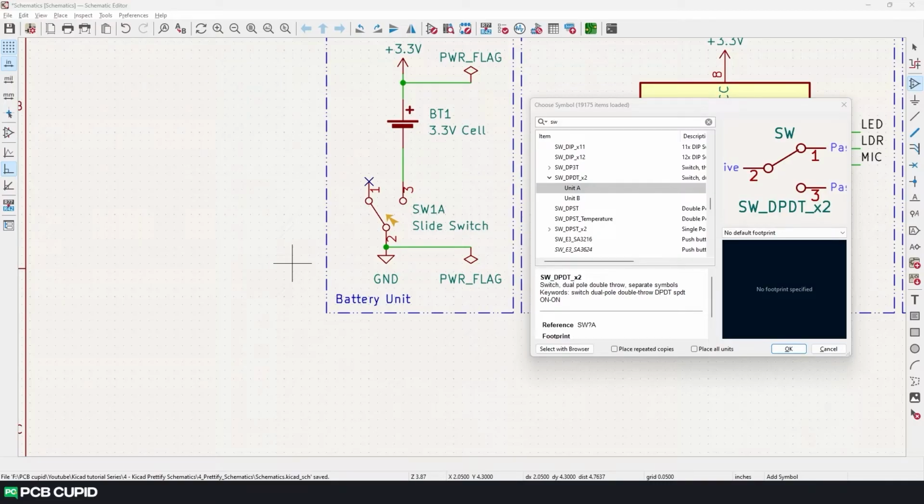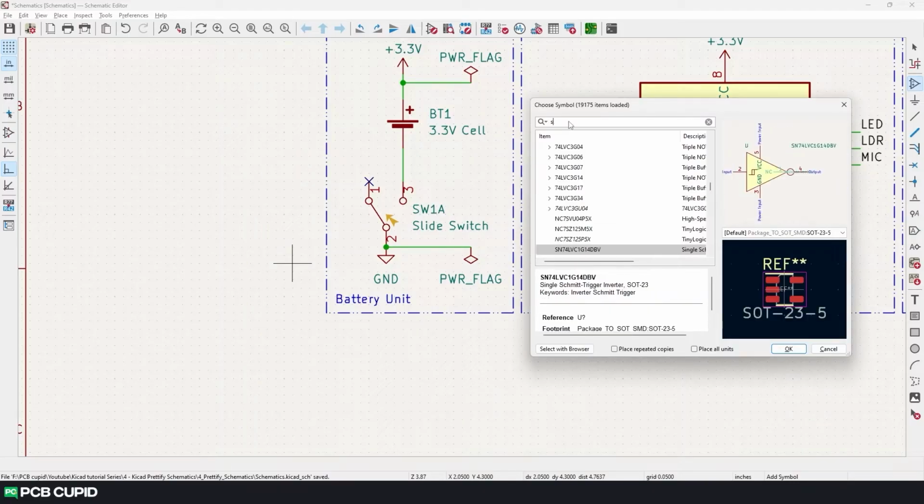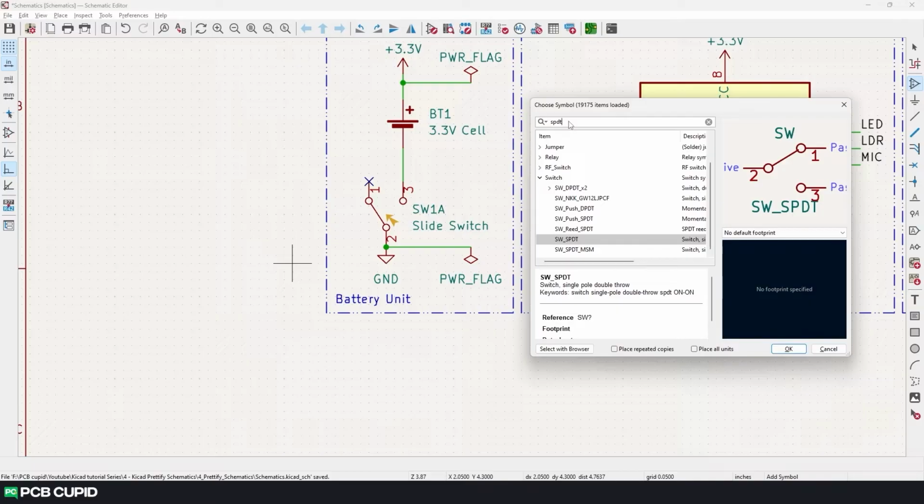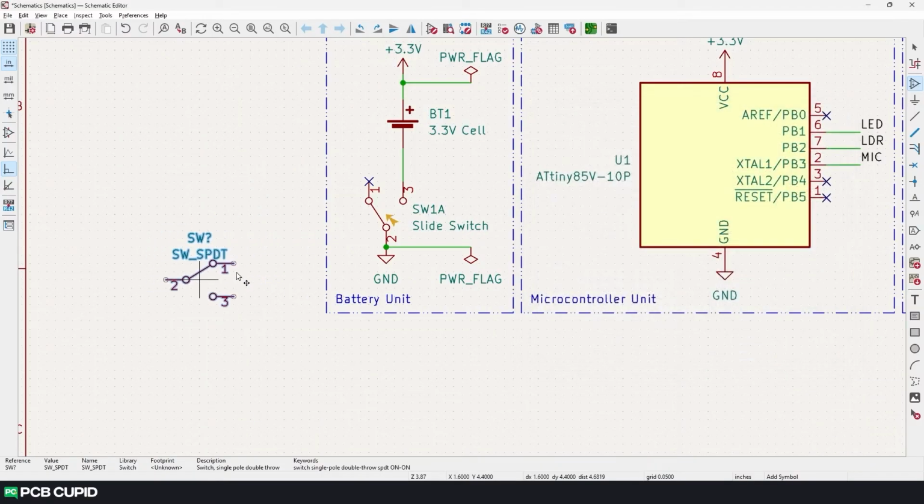We can also go ahead with the warning and go to PCB development. Because this is just a symbol that represents the switch, it doesn't have any physical dimension or shape of the switch assigned to it. But I would prefer to fix the warning before we move further. So let's search for single pole double throw switch and replace it with the existing switch.